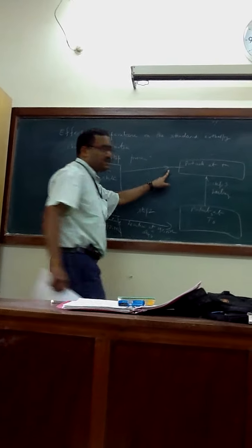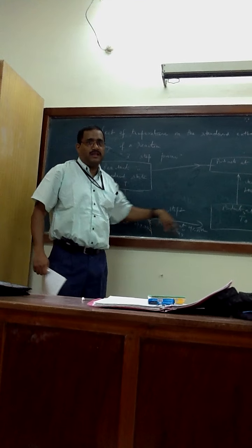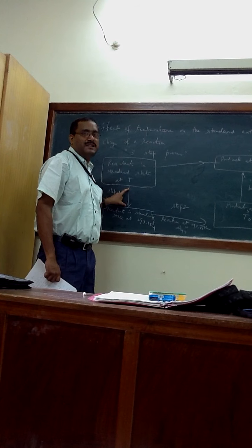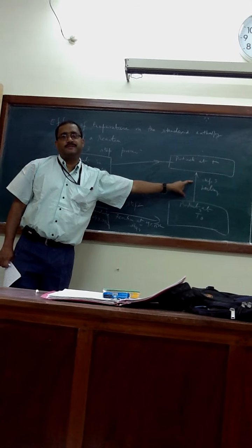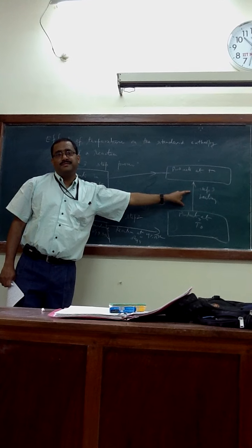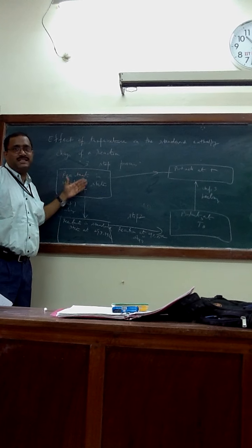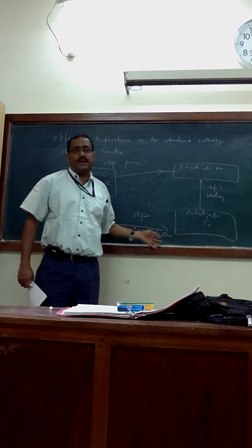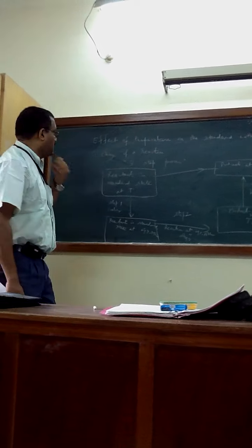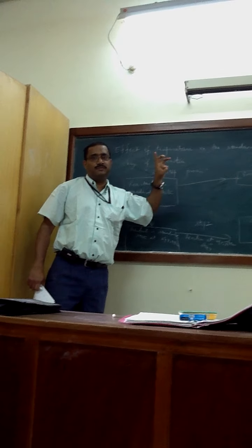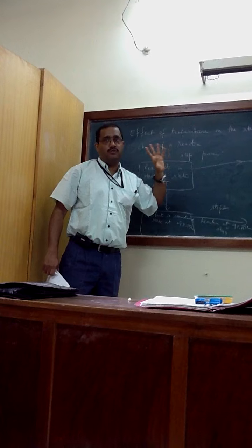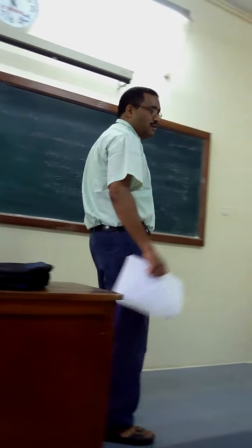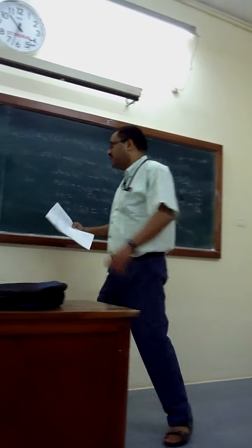I cannot go straight to do a calculation. I have to go by these steps. This step is okay, we have the heat of reaction. This step requires the specific heat, and this step requires the specific heat. This means I am having a sensible heat change, Cp delta T. So what actually happens in the heat of reaction for this? We will be having 3 terms: one is the heat of reaction term at T0 and 2 terms comprising the Cp's. Clear? This is the most rational way one can do the calculation.